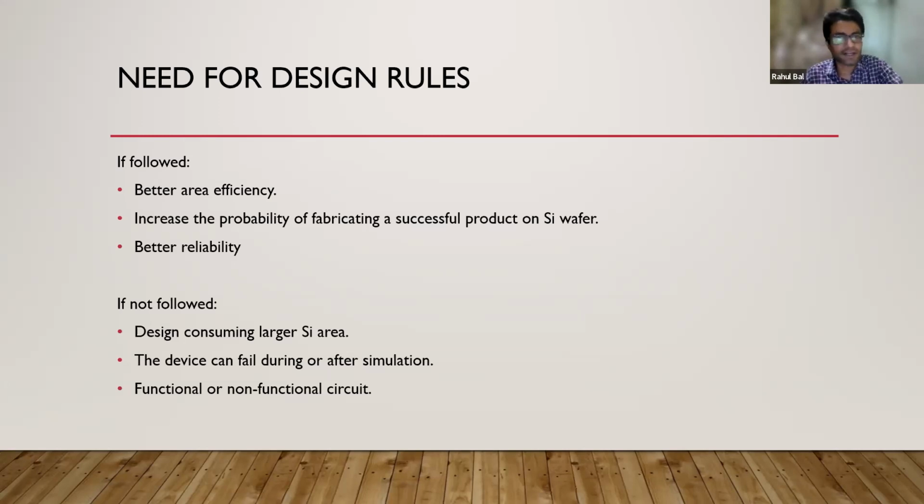And if they are not followed, then the consumption of silicon area will be larger, because you are placing the components randomly. There are no rules you are following, so the components get placed randomly, and they may require a larger area of silicon. The device can fail during or after the simulation, so there are chances of failure of the device if you are not following the design rules. And lastly, a functional or non-functional circuit.